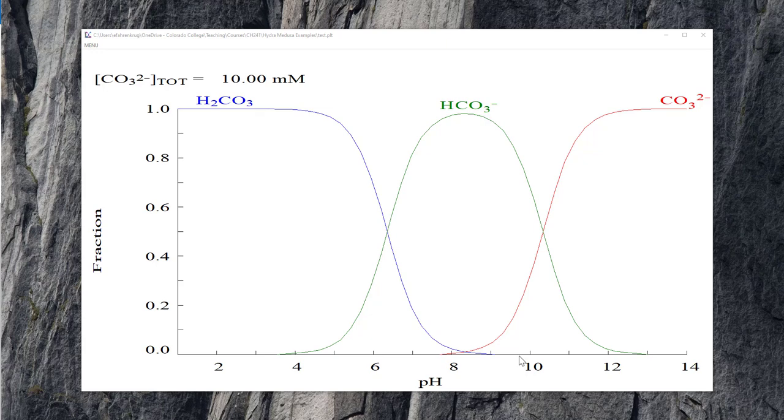And actually, to have appreciable amounts of carbonate in an alkalinity titration, you can see that we would need to have pHs in excess of 8, really in excess of 9 to be consequential. So pretty alkaline waters to have any measurable amount of the carbonate ion in the overall carbonic acid equilibrium for that water.